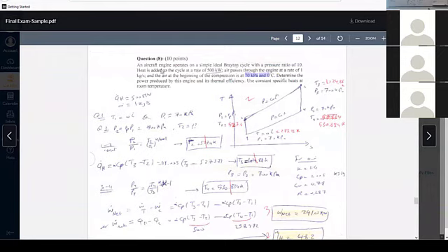And he gives you the heat added. This heat added is related between T3 and T4. So Q high, which is m C delta T, you have the mass flow rate, which was 1 here; it can be different in the exam. You have Cp, which is air, 1.005 from table A-2a. You have T3, which you don't know, and you have T2, which you got from the isentropic relation between 1 and 2. You can get T3.